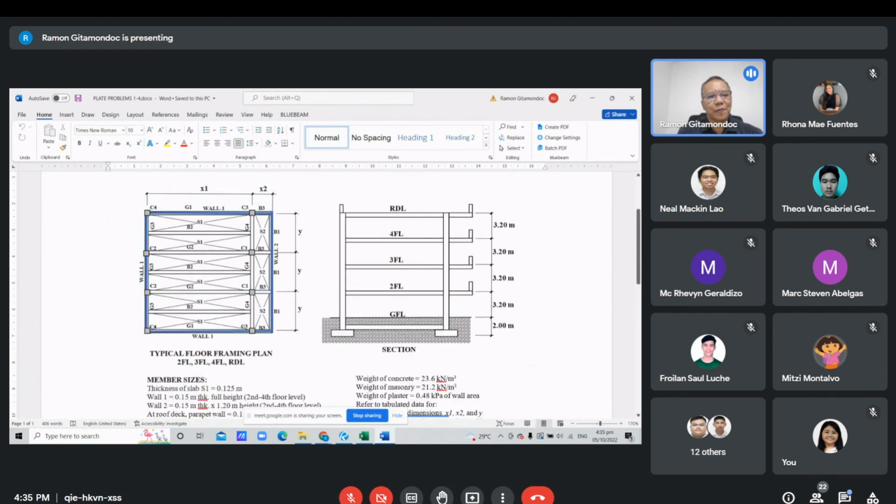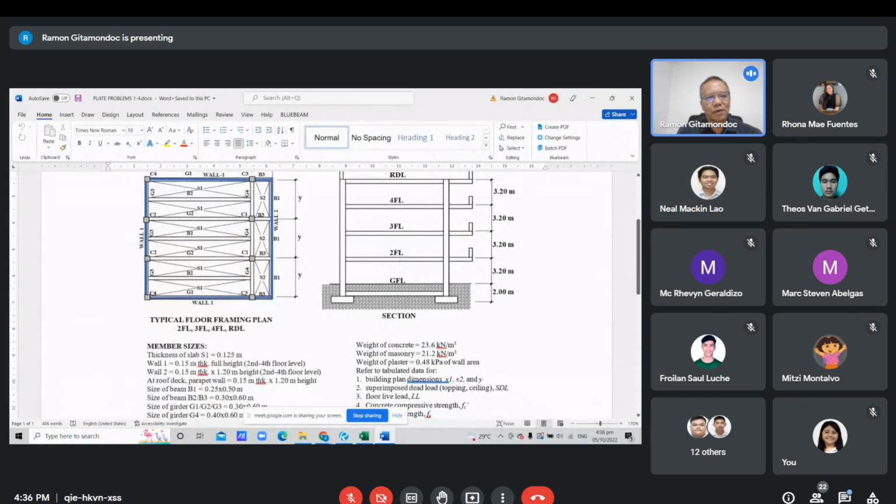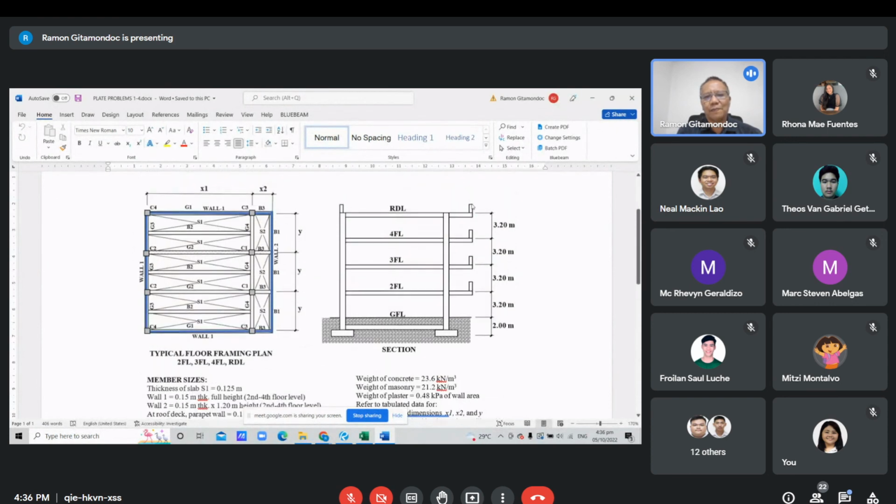It is full height because that is the property line there, no? So this side is closed, this side too. Now wall 2 is at the entrance. Of course, it is open because it is the building frontage. As shown in this section, it is open, no? It is not full height, it's only 1.2 meter height. So the roof parapet is all around, as shown here, at the top, around the perimeter. So it is only at the lower floors that the walls are full height, along the three sides of your building.